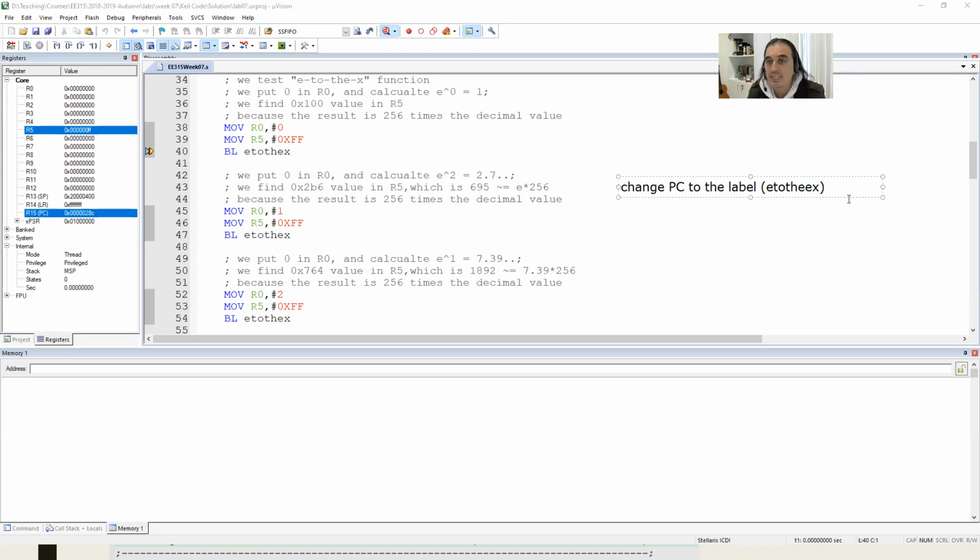No. The second thing is write the next PC value, I'll call it PC plus 1, to LR. Okay. What is the current PC value? The current PC value is the address of the current instruction. So this current instruction is written inside the instruction memory in an address.